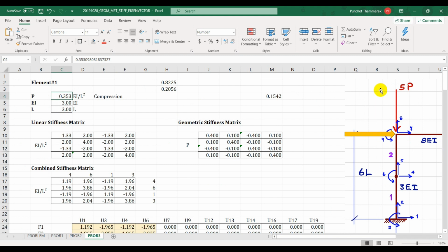So keep P like the universal unit. Okay. Then you start with a small load. Apply a small load, run the analysis, and then you get the displacement response versus the load. You make the load into many small steps. So just keep increasing the load. Small increment, small increment, small increment, until you can see the softening of your structure.